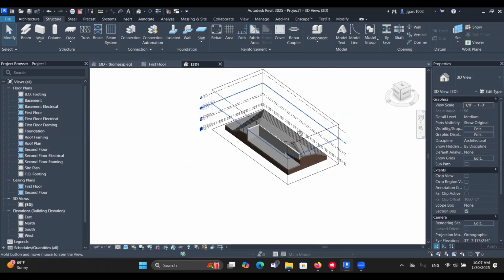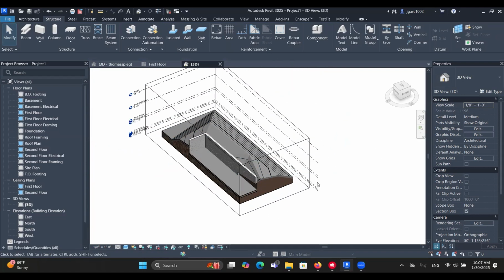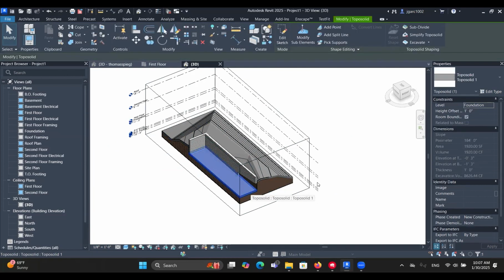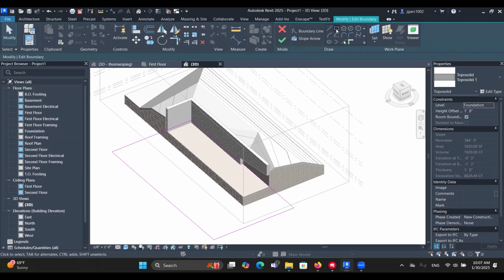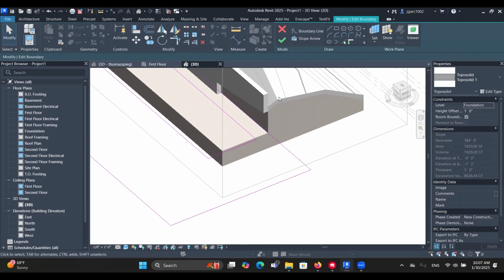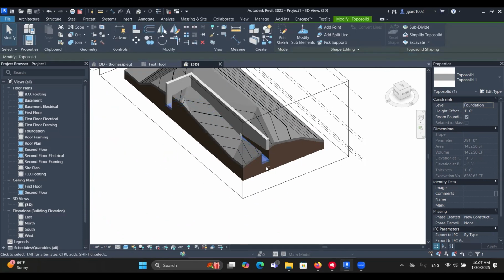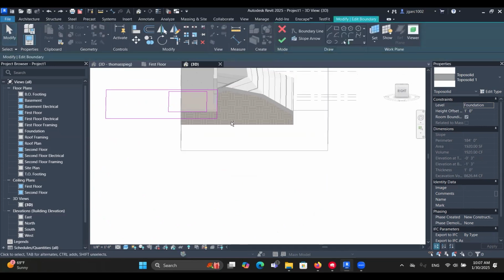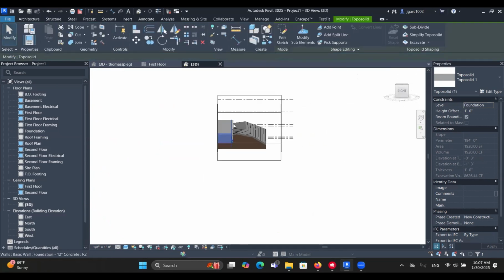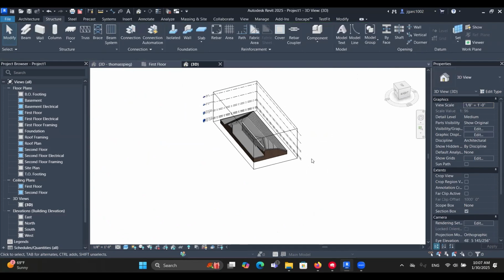Okay, so as far as editing, instead of just selecting an object like this, you double click it, and you're going to have the boundary again. If you do any lines in it, like this, if you do any openings in it, it's going to create an actual opening, and it's going to let the topography go back in because it's an excavate parameter. So in this case we won't do it, but if you were to do it, that's the way to do it.